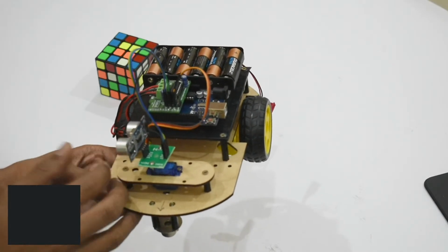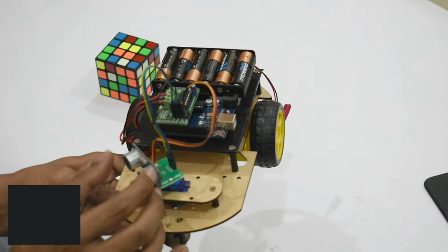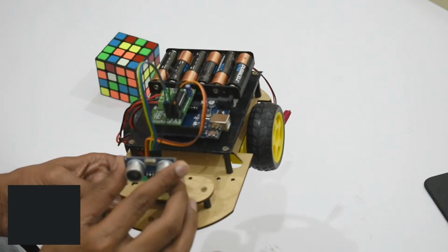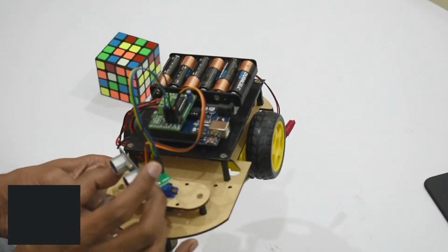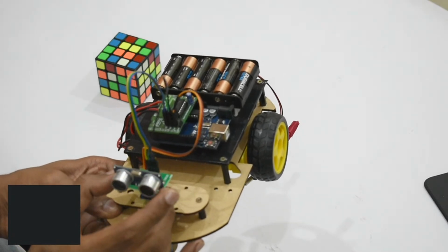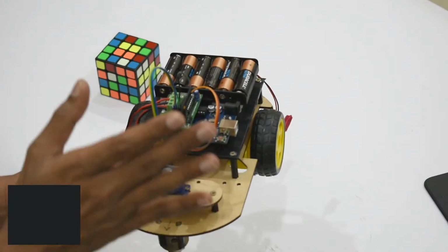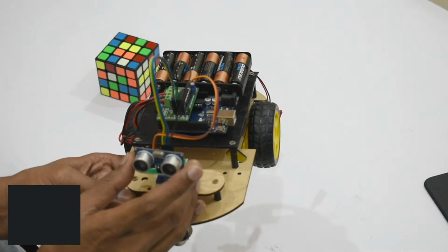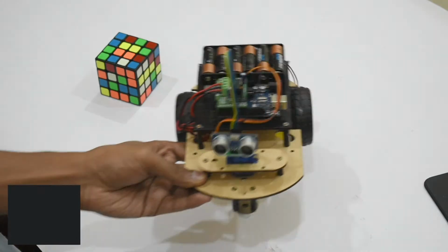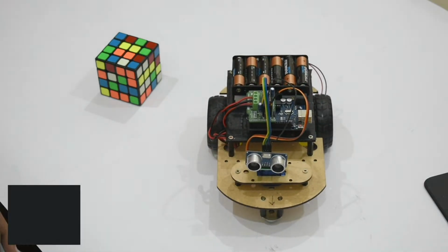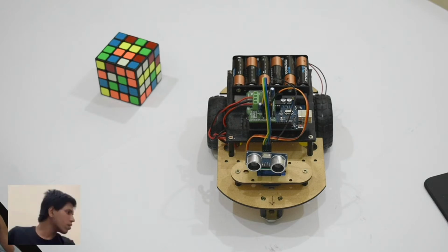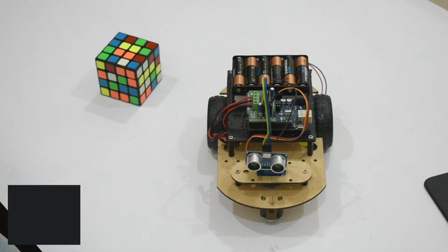But at the very beginning when the car starts, your servo can be at any angle. So what I'm saying is, by default, when the code starts, come to the 90 degrees angle, because that is going to be your front portion. So I'm telling my code that the servo is attached to pin number 9. Now come to the 90 degrees angle, and then it's going to stay at the 90 degrees angle.